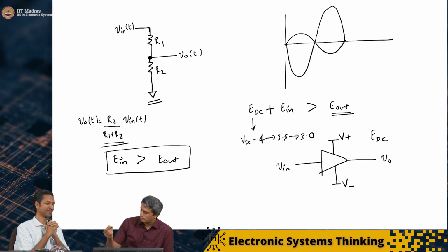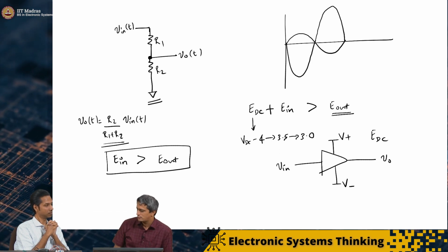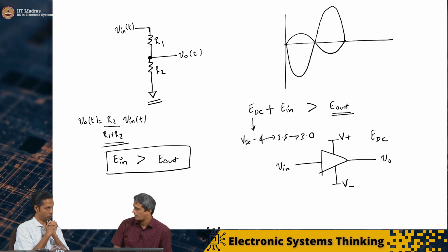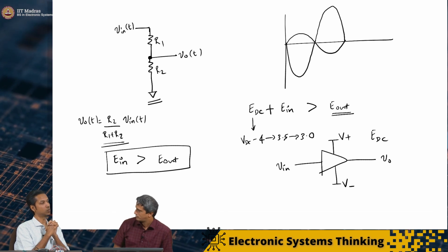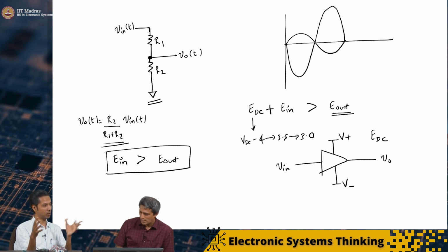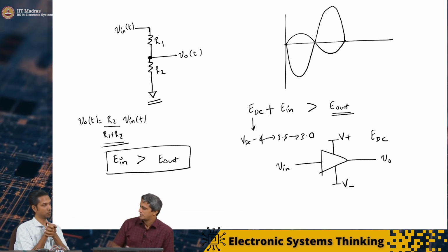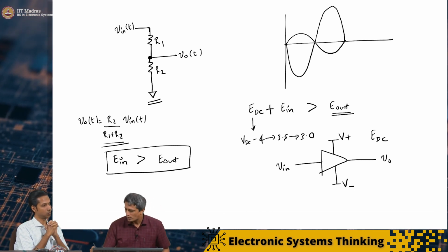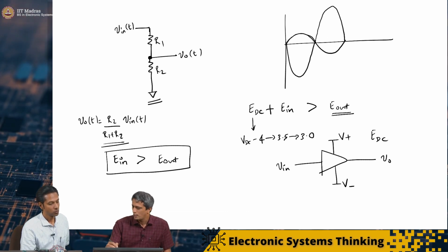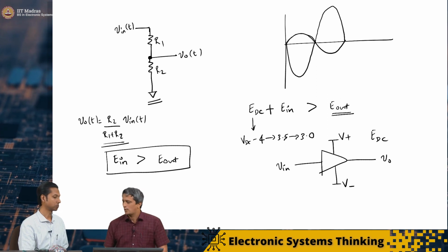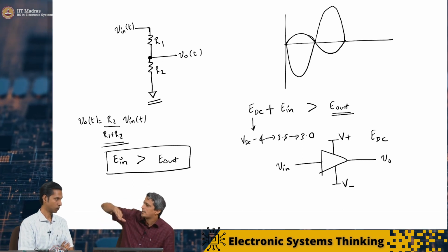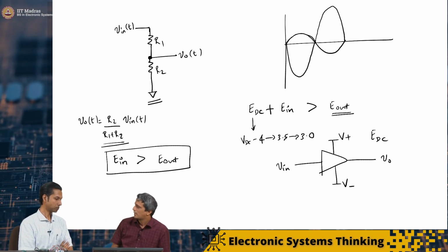All right. The next question that I really have, and we also discussed it when we discussed the non-inverting amplifier, is this omega naught. What do you think will happen? The highest frequency I can operate. Frequency, we increase it, can the output... So essentially what we are saying in this particular case is the input is going reasonably slowly. The output seems to be following this input. Output is just following, it may be inverted, non-inverted, doesn't matter, but it is following the input at that speed without any delay.